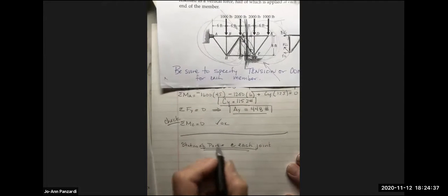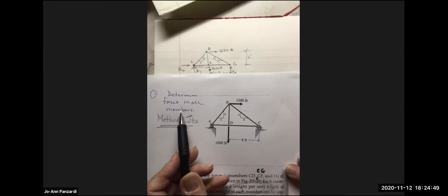So this is a rigid body because all the forces are applied at different points along the body, and we wound up doing sum of the moments. But for joints, they are telling us to do statics of particles. Why? Because we're looking at each joint. So everybody look at this for a minute. Everybody looking up here?